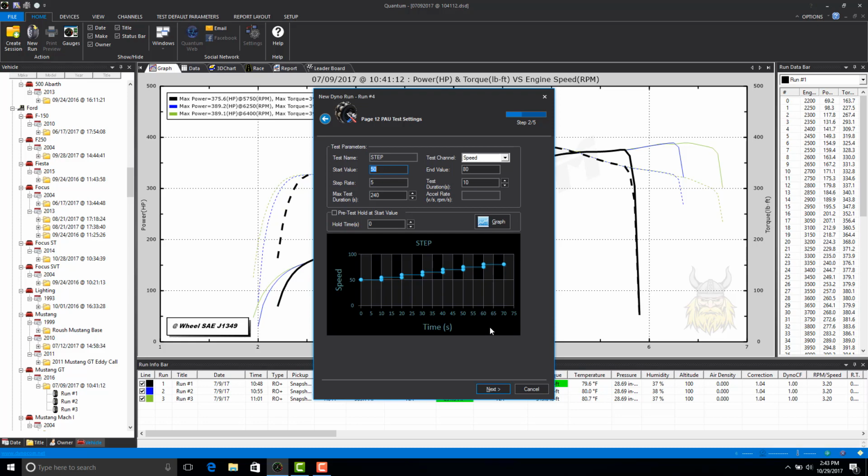Whereas when you're doing Mode 1, you're typically going up load and then stepping to another RPM and going up columns. So this is going to go across rows, where Mode 1 goes up columns. So you just can do different rows in this model rather than columns in Mode 1. The advantage here is you get to log the data. This is not as effective if you have a real-time tuning capability. I would recommend Mode 1's, steady state and RPM on the handheld. But if you're doing a flash tune where you're going to log and then make changes based on the log values and then reflash, this is a very effective way to do that.